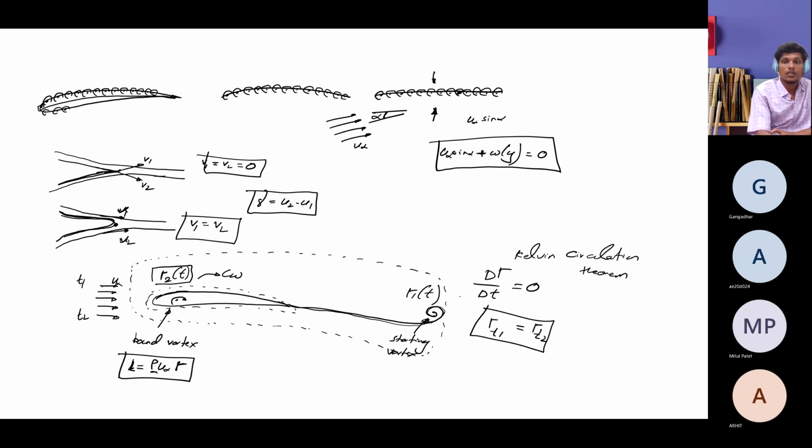And this Kelvin circulation theorem is very useful not only for modeling this infinite aerofoil. For finite wing also, we are using this Kelvin circulation theorem as a base to construct its modeling.